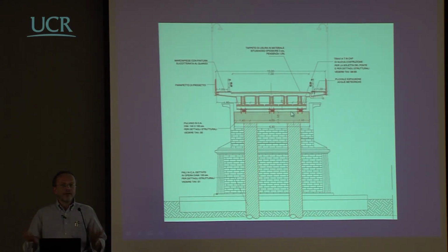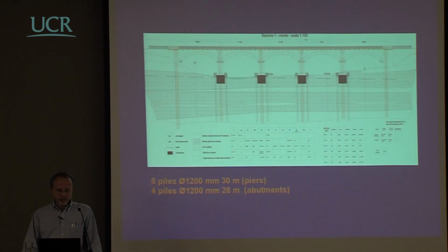If you start with a force-based approach, you have to start with an acceleration spectrum, and you don't know how to deal with the isolated structure. You know that years ago there were proposals to use a kind of corrected acceleration spectrum, which was elastic at periods shorter than a certain level, and reduced because of the isolation system beyond a certain period, which is something that doesn't work at all. But anyway, this is just the transversal view of the bridge.